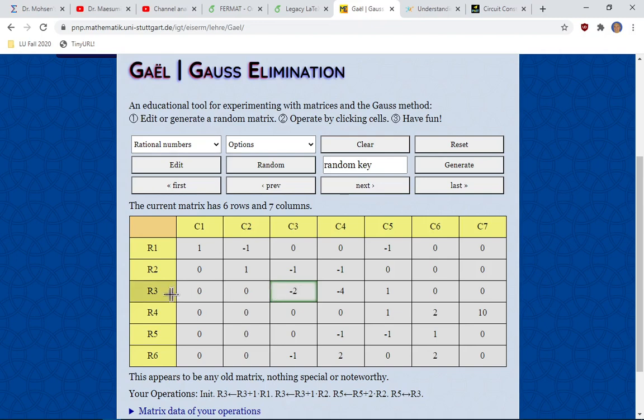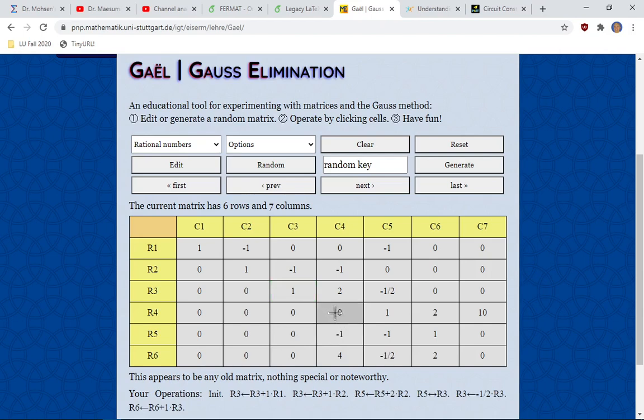I normalize by dividing by that number, so I divided by -2, use this as a pivot, eliminate that one, do another swap, normalize this to be 1 so it's easy to follow. This is pivot, this is target. Now this is a pivot, this is my target. I divide this last equation by 15, so I know my last current is going to be 3.